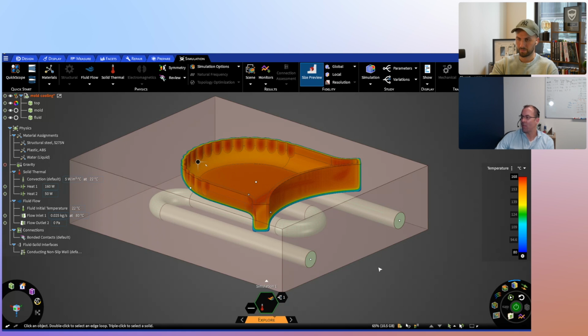Okay, what's the average exit temperature here? Yeah, we get that within a degree. What's the exact heat transfer coefficient on this bend versus that bend? Maybe we're a few percent off here and there. But again, the level of engineering of digging into the exact local heat transfer coefficient is rarely done.